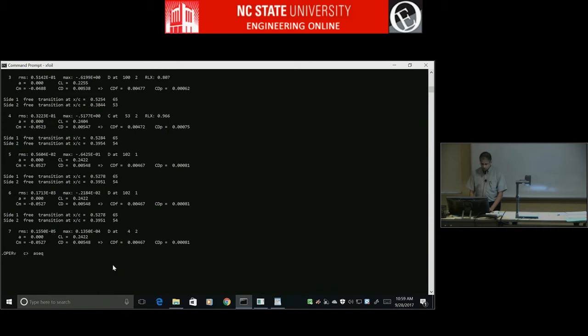What it'll do here is, let's say I do first alpha. I've already run angle of attack 0. So if I say first alpha of 0, it's going to use the converged boundary layer from the previous calculation and use that as the initial starting point, and it'll go to the next alpha. Because I've already converged 0, it'll converge the first alpha, which is 0.